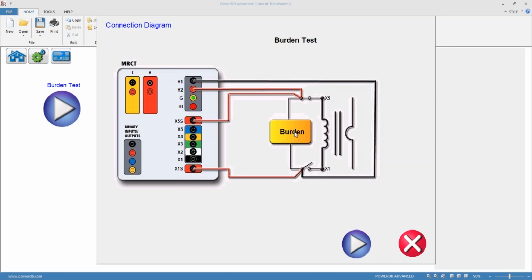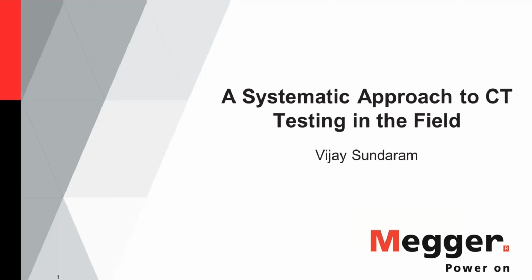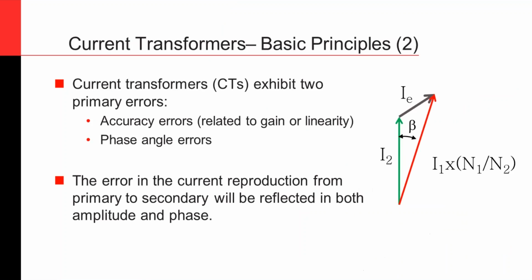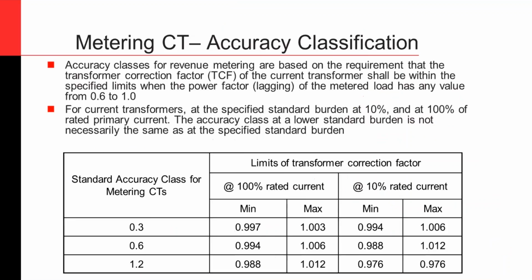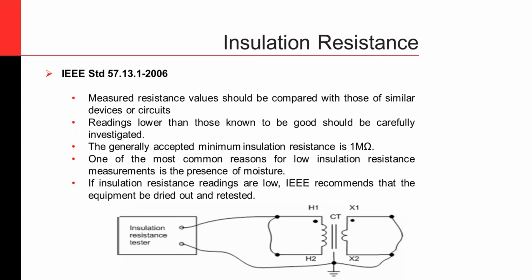Another question, from Mr. Nuno Montero: during the insulation test, does polarity matter? Does it play a role during an insulation test? My straight answer would be no. It doesn't matter during an insulation test, because you're just applying voltage and measuring the current, or measuring the leakage current.